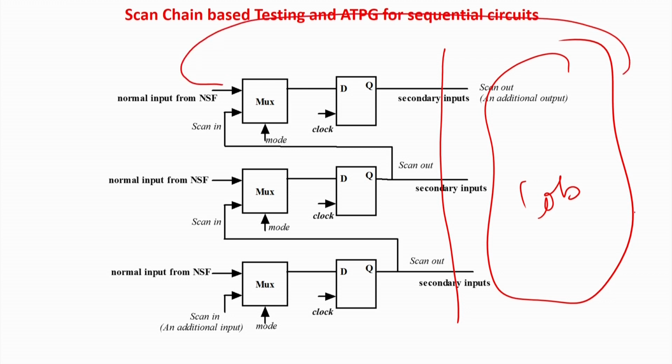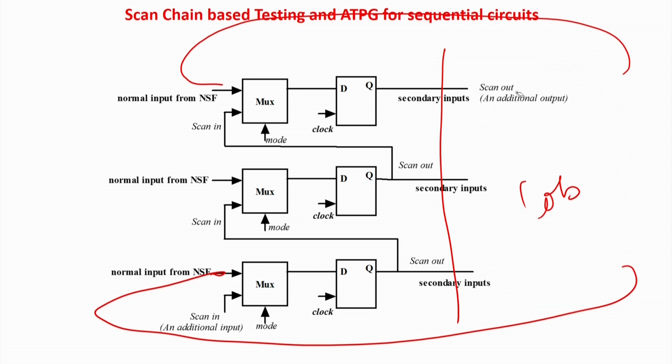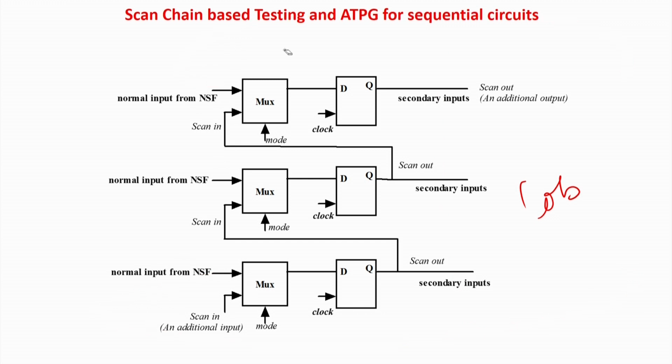The outputs of the flip flops again go to the combinational cloud, that is your NSF block, and this is a typical structure of a sequential circuit. I need not draw over this, but say that somehow I need to make it 1, 1 and 0. I need to do that. So basically I will have to either set or reset. In this case 6 lines will be output, but you can set and reset in one go, because this is set, this is set and this is reset.